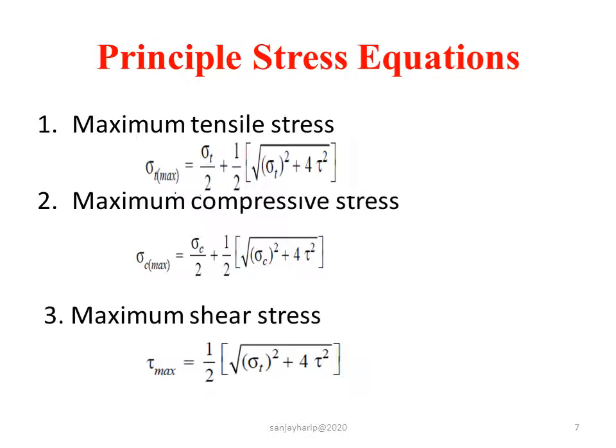There are many cases when machine members are subjected to combined stresses, that is tensile, compressive and shear. In shafts or C-frames, there are direct tensile or compressive stresses due to force and shear stress due to torsion. In a crankshaft, there are both torsion and bending stresses. In such cases, maximum principal stresses due to the combination of tension, compression and shear may be considered. Maximum values can be calculated by using these principal stress equations.